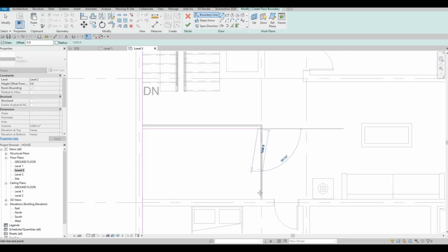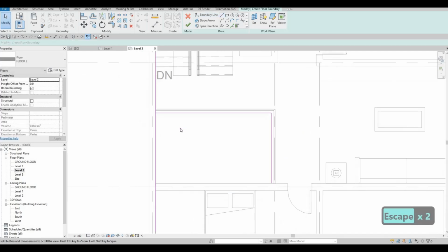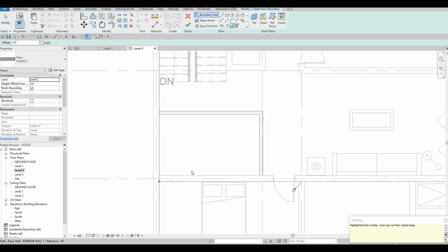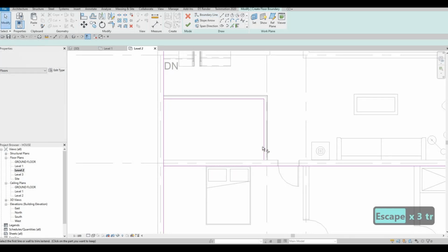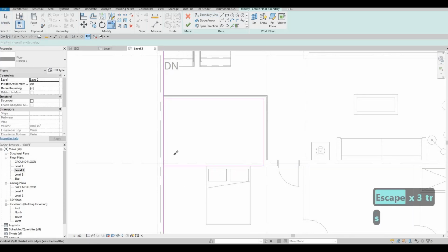Of course, there should be a gap between the railing and between here. And then now, what I'm gonna do is I'm going to pick this line actually, and then let's trim and extend here, and then SL here to slice it up, and then trim and extend right here as well.